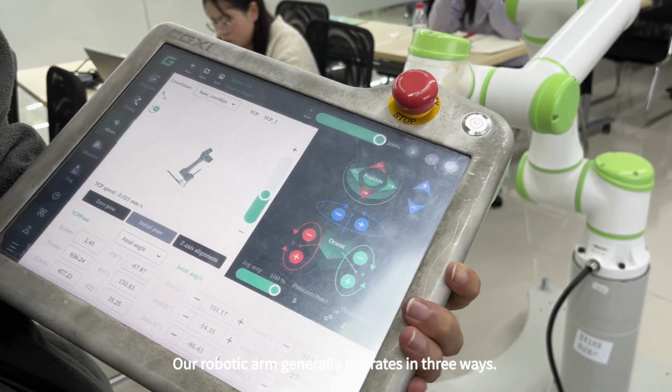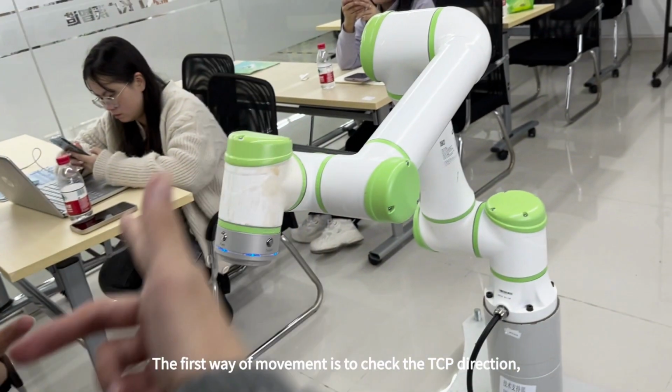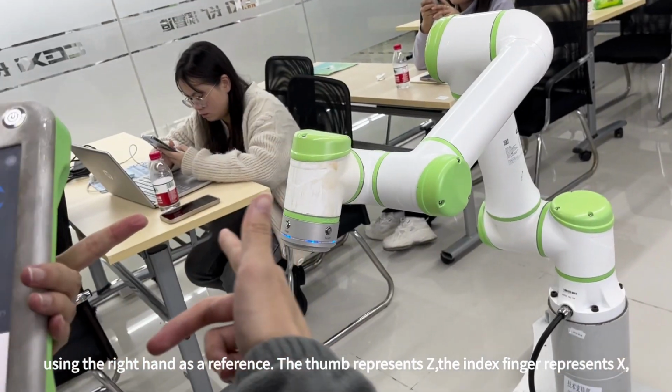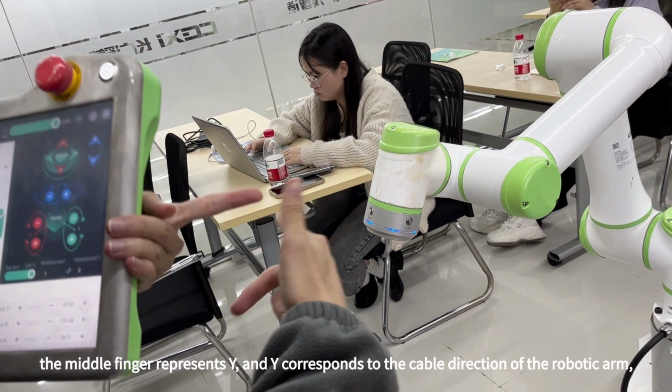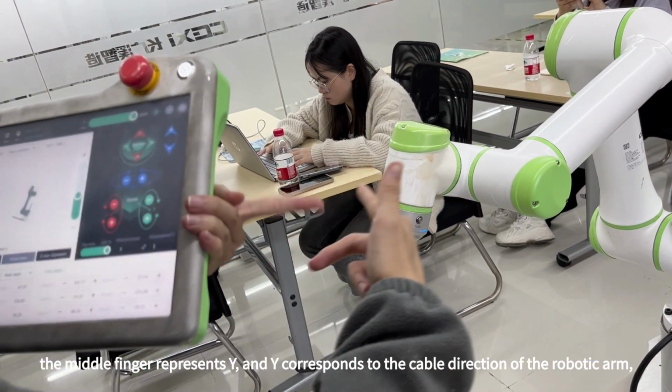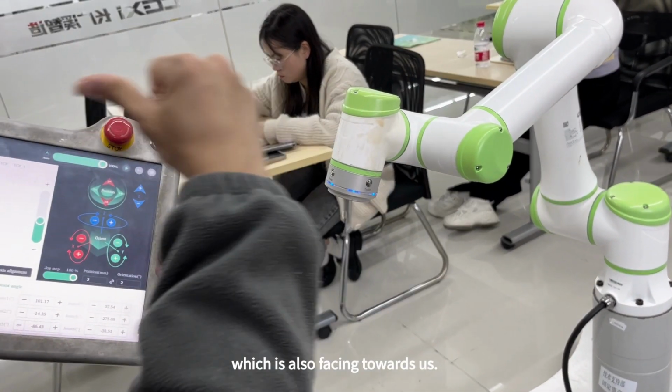Our robotic arm generally operates in 3 ways. The first way of movement is to check the TCP direction. Using the right hand as a reference, the thumb represents Z, the index finger represents X, the middle finger represents Y, and Y corresponds to the cable direction of the robotic arm, which is also facing towards us.